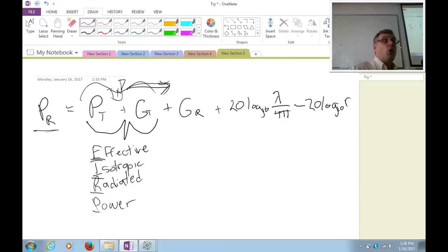But when they go to report, they've also got a transmit antenna. It's an array of circularly polarized bent dipoles that they use. And collectively, you're getting a lot of gain at the horizon. Maybe, let's say 10 dBi. I think they get a little bit more, maybe like 11 or 12 dBi on their realistic tower. But the point is that that's a factor of 10 in the linear scale, at least, going to the horizon.